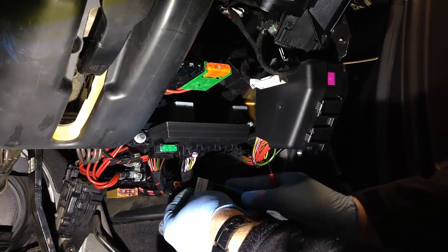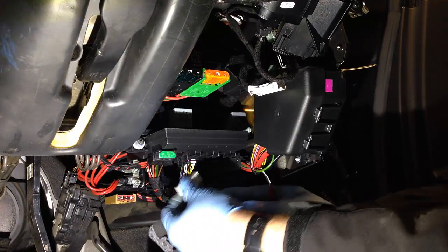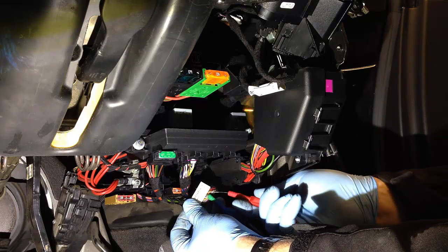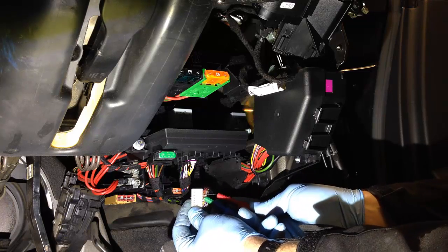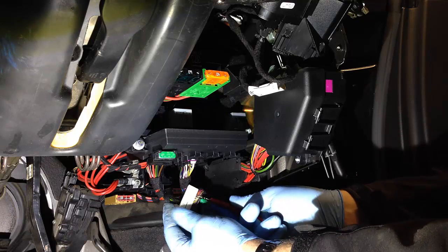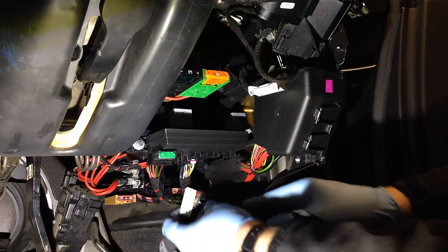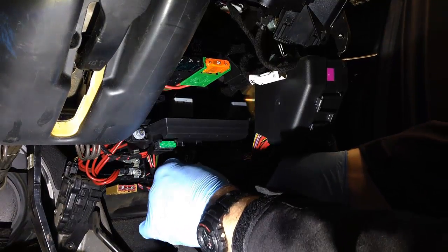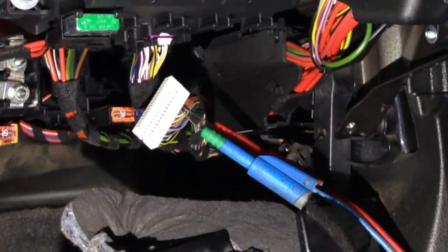What we're looking for is, we'll try these disconnected first of all, 12 and 13. We'll just back probe those pins there. Orange, green, orange and brown. We'll try not to damage the pins is the trick here. We want to get them through so they're making contact, but we don't want to short them out, and we don't necessarily want to bend those pins. So let's just see what we can get there. They're connected.